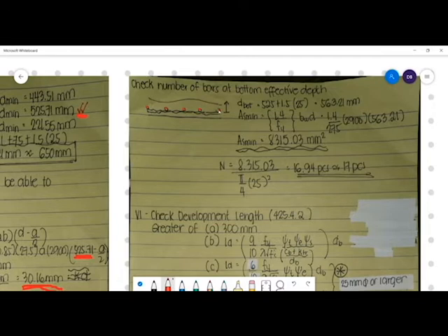From the center of yung mga pinarang pula na reinforcement up to the top of the footing. Pero what about this one? So this one, yung nasa ilalim niya, up to the top of the footing. So we determine the depth at the bottom, 525 plus 1.5 multiplied by 25,